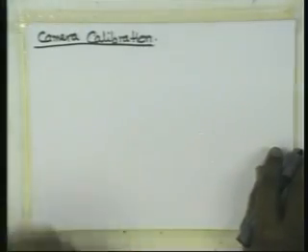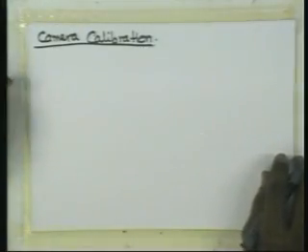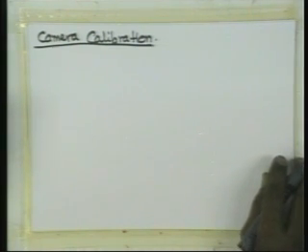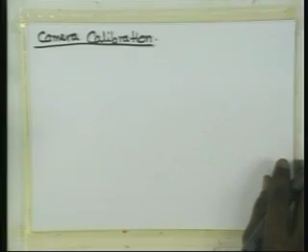What does camera calibration mean? It basically means that I want to determine the transformation matrix that I have talked about, which is the product of P times C times R times T. Now, if I compute it from the pan angle, the tilt angle, every error in each of these quantities is going to lead to an error in the transformation matrix, right.